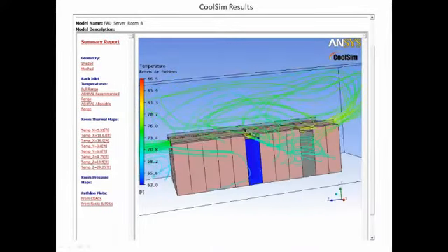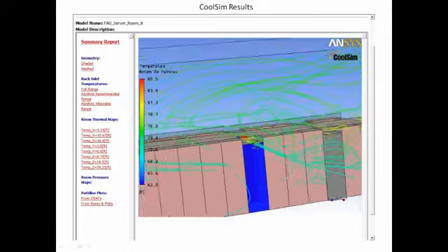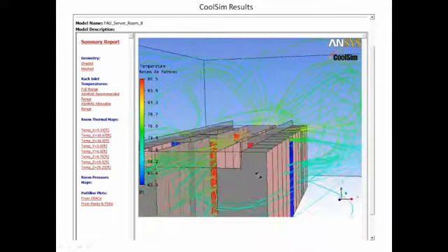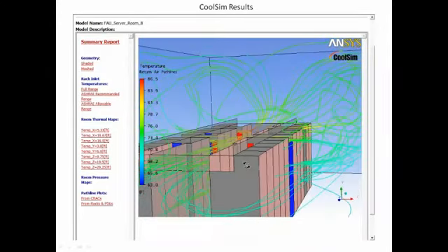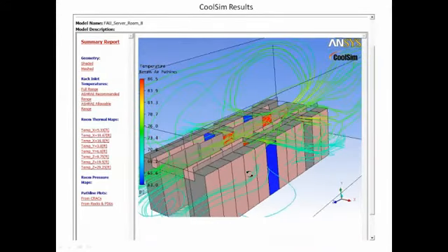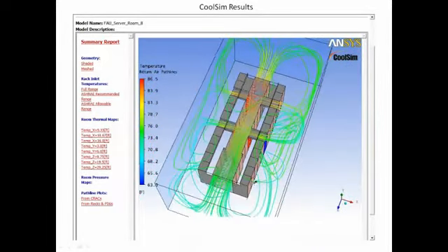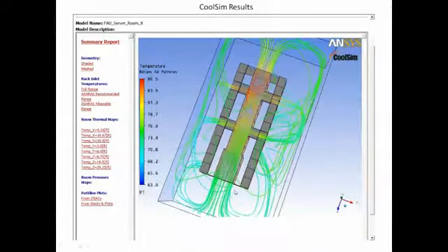There's a crack here above this one because the cooling unit is not quite as tall as the containment system, and there's also another one here at the end. And you can see the racks are blowing their air out and being fed back into themselves. They're recirculating. They have to because they have no other place to get their air.